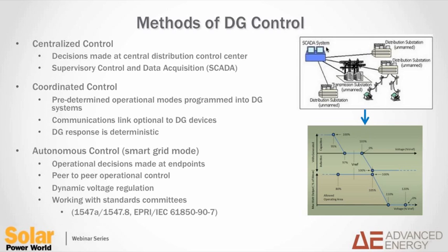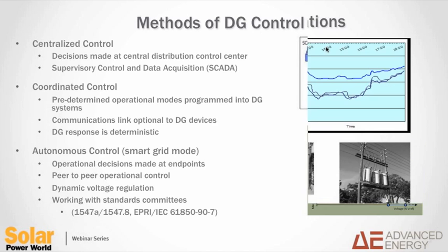We're going to take a look at an example of coordinated control here in just a second with scheduled power factor, but I think you should get from this that you really have to be extremely flexible in what the inverter control functions can offer, everything from direct control all the way down to a highly configurable autonomous mode in the network the farther you go down.